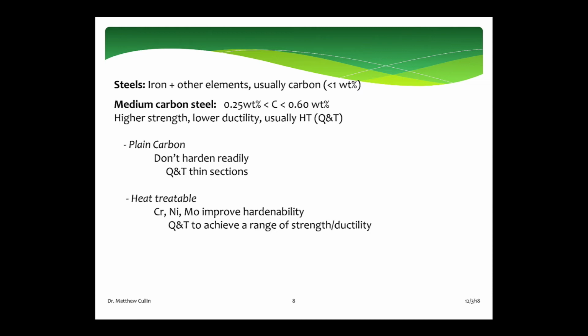If you favor the ductility, then you may use it in the normalized state. But again, you're trading off. You're essentially paying for medium carbon steel, but you're saying, I like the higher strength I can achieve. Maybe I can get 70, 80, 90 KSI, but I don't want to heat treat it because I know I'm going to give up ductility in order to do that.